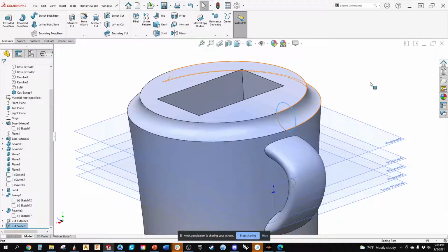And really, one of the things, once we have gone through these tools, we're going to start going through, and this will be your next assignment actually, is you're going to take a product and you're going to break it down into the geometric parts, and then you're going to call out, oh, this would be an extrude, this would be a cut, I would make this as a revolve.